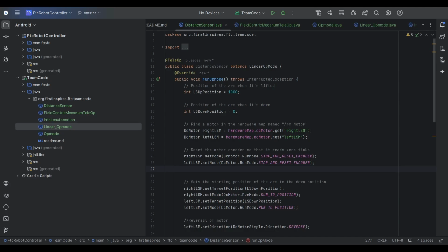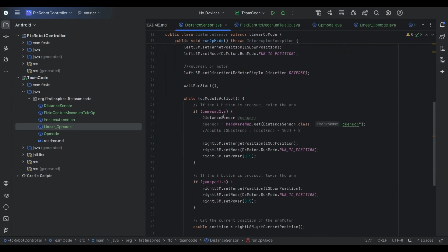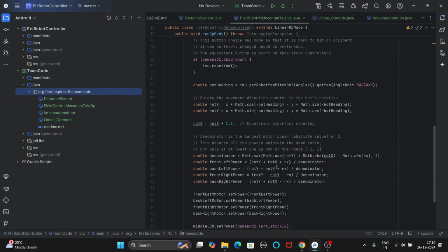FTC programming logic follows a basic initialize, name, give value, the basis for coding the components. So for example, you can see we initialize, we can give a value, and we can set different modes for the same. There's a naming and initialization line, then there's an action line which gives a certain value for the component. This value can mean different things for different commands and components. So for example, when we're coding the motors, the number ranges between 0 and 1, where a higher number means a faster rotation speed.